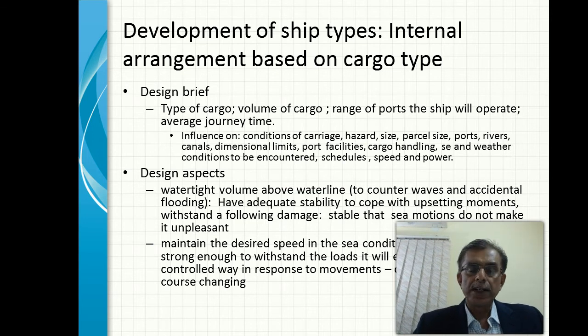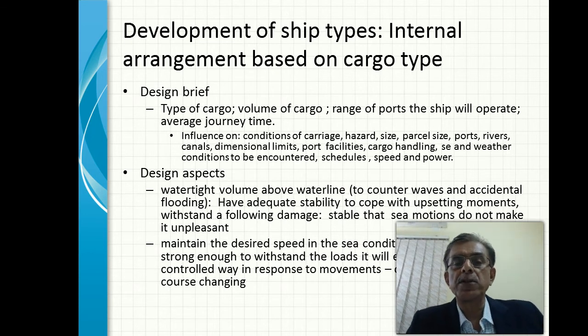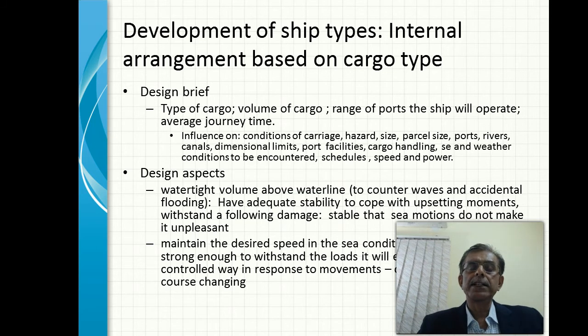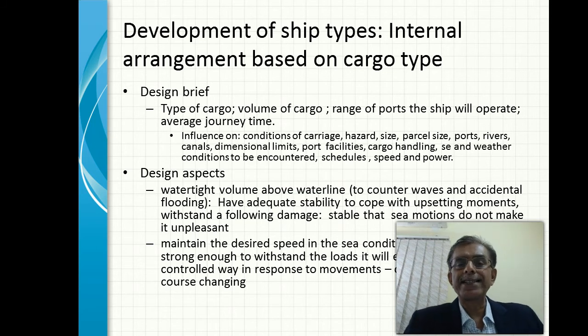Further, in the design context, what are the ports and the rivers to be traversed, or if there are special zones to be traversed, it may have an impact on the dimensions of the ship. And the port facilities also has a bearing on the gear that has to be designed on and carried on the ship. Weather conditions, ship speed, installed power, all these factors have to be taken into consideration, and the fundamental basic design